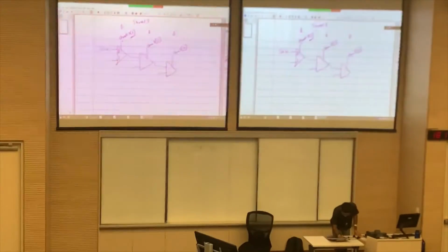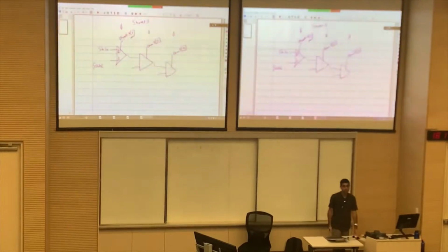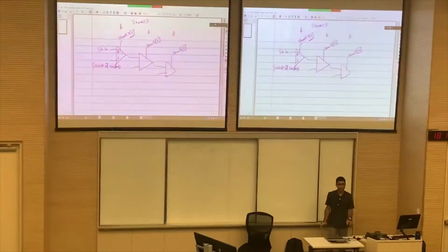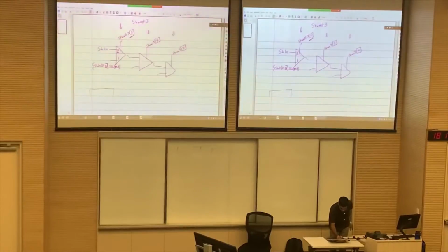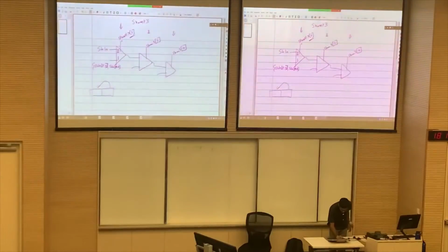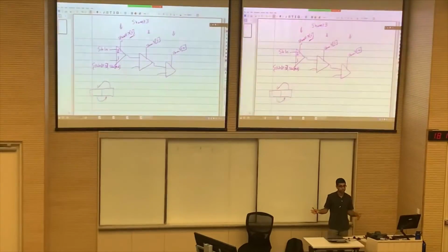So this will be SH in bits 3 down to 0, concatenated with SH in bits 7 down to 4. So you are basically taking the 2 halves and interchanging. So if this is your 8-bit value, rotation by an amount 4 means this half comes here, this half goes here, right? So that's what we do.